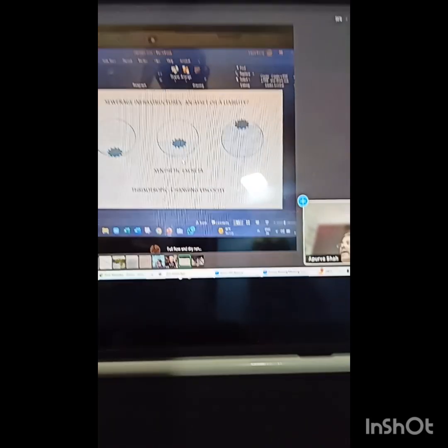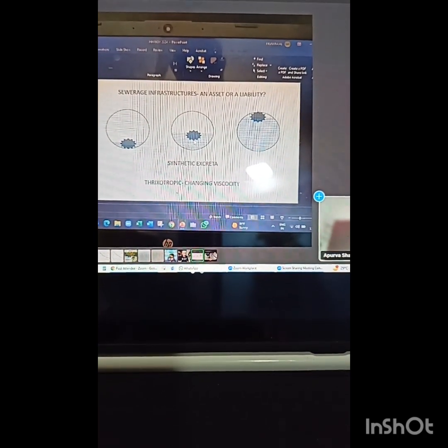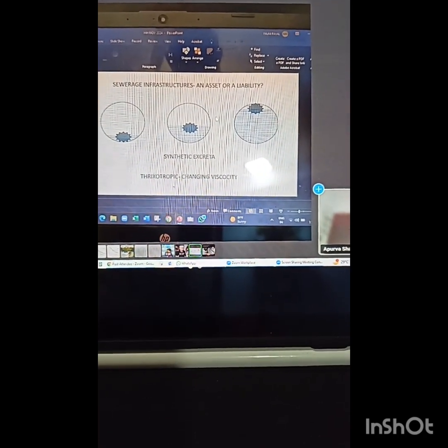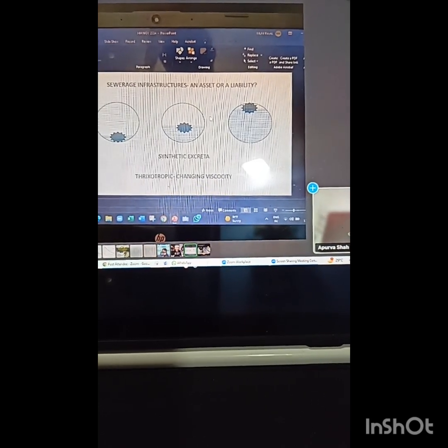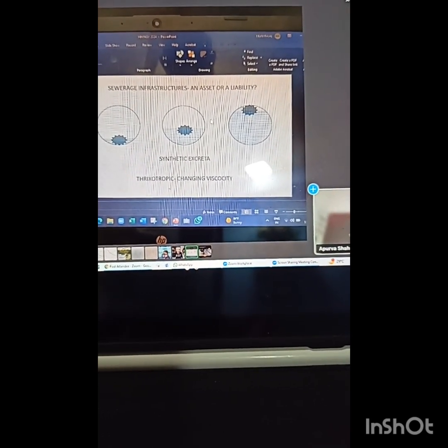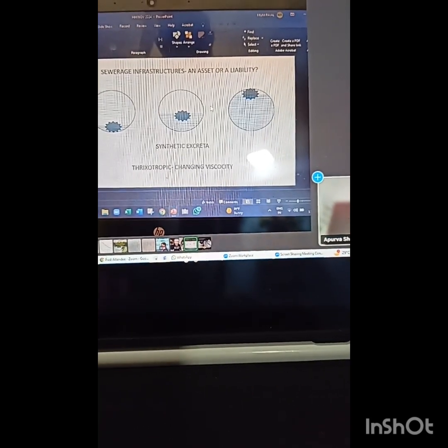The flow of liquid and the solids in the pipe is designed as per the hydraulic design. The pipe diameter is selected for the peak flow. Peak flow is normally 3 hours. For the rest of the 20 hours or so, the pipeline has an average flow or a very minimal flow, which is 5 to 10% of the daily average flow per hour or per minute.